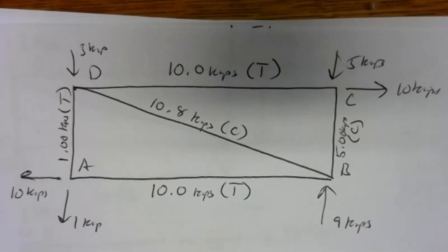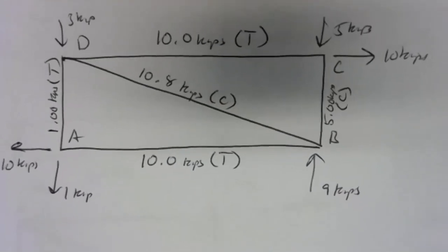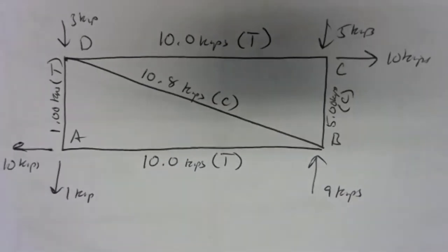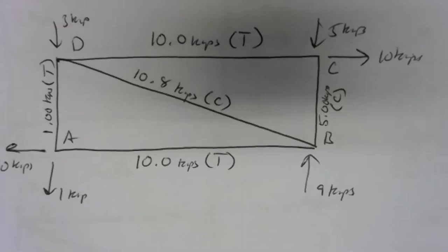So it's worth staring at these for a little while and trying to figure out how this would work. A really good visualization technique is to imagine it deforming. Imagine it changing shape. Imagine building this and watching it try to start to fall over. How is it going to move and what's going to fight it from moving? That'll give you some idea of how things are in tension or compression.